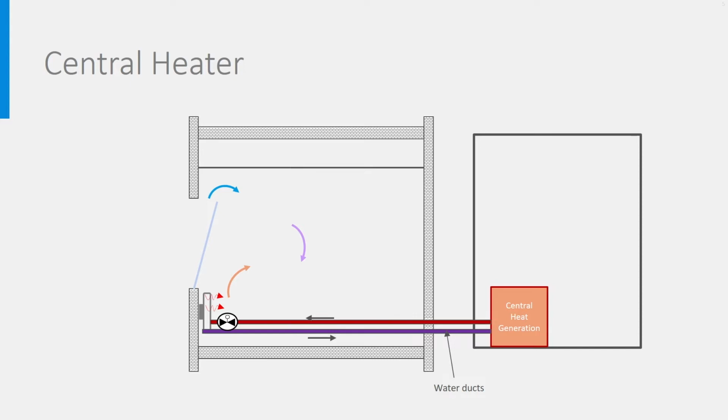Nowadays, heat pumps are also used more and more because of their high efficiency. When district heating is applied, the central heat generator is just a heat exchanger connected to the outdoor heat grid. Observe the valve. The radiators can mostly be controlled at room level. Very often, there is also a room thermostat telling the heat generator when to produce heat and when to stop.